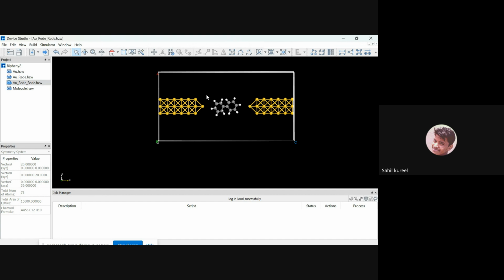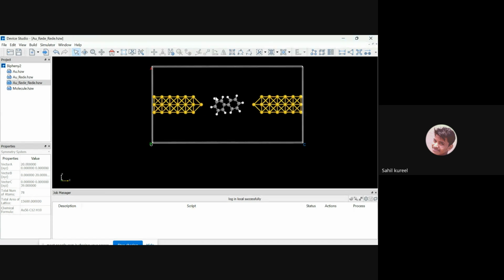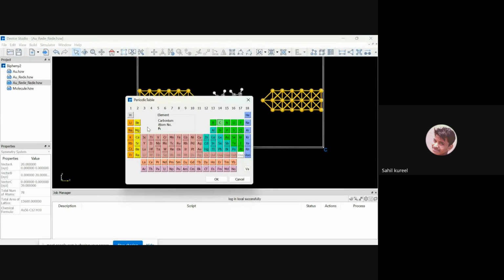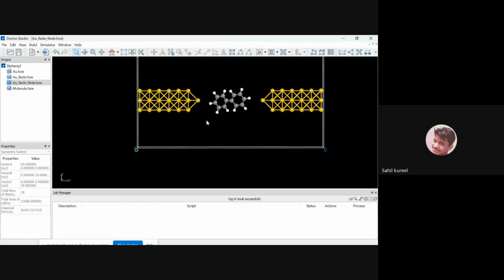Okay, now I'm going to move that forward. You can click that, and now I'm going to add here the nitrogen atoms because we need to also connect that bond with these molecules. You need to move to the add atoms option, plus, simply select that nitrogen and then click OK and click here that nitrogen atom.